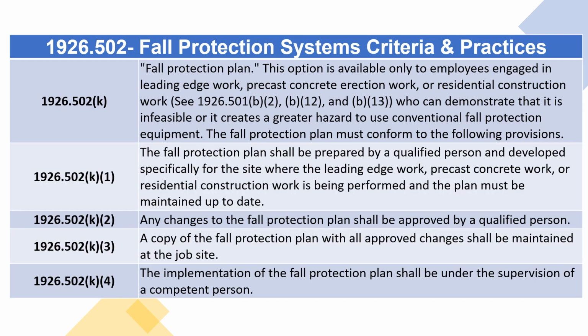1926.502 K. Fall Protection Plan. This option is available only to employees engaged in leading edge work, precast concrete erection work, or residential construction work (see 1926.501 B2, B12, and B13) who can demonstrate that it is infeasible or it creates a greater hazard to use conventional fall protection equipment. The fall protection plan must conform to the following provisions.